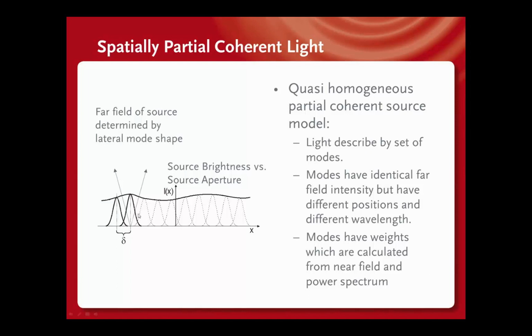The shape of the modes actually depends on the far field intensity of the LED. That means if you have, for example, a measurement of the radiant intensity of an LED, then it is possible to calculate the mode shape from the radiant intensity of the LED.